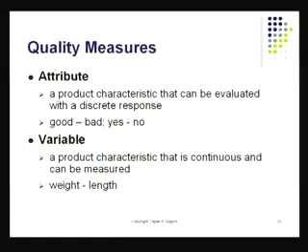You might be doing a bit of witch hunting once in a while. That means the process is fine, but the chart gave a wrong signal because of the random combination of things. It's also possible, of course, that the process itself has become worse. It has become bad. But even if it is bad, it turns out that the chart is within your control limits. That's also a wrong signal. In fact, you're not getting the signal when you should be getting a signal. So let's try to see what we could do.